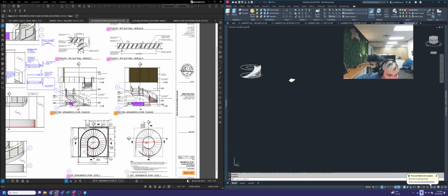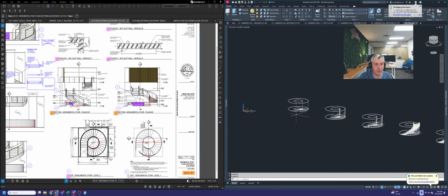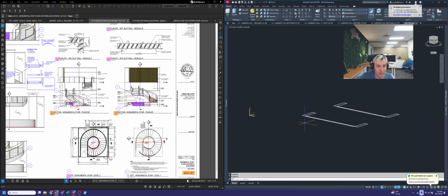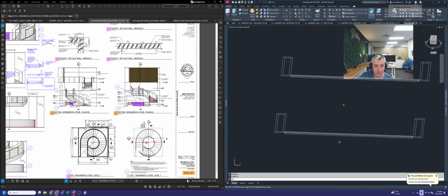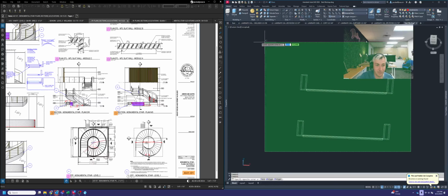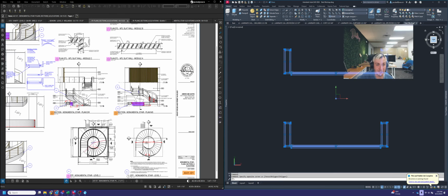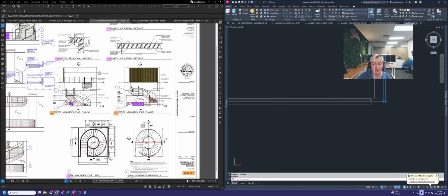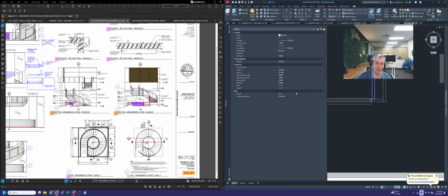One thing you can see is that what you really want to start with is your section view first. Anytime you sweep a model, it's pretty much the same deal. You want a model that has a bunch of closed polylines. Each piece of geometry needs to be closed. If I click on that and go into properties, you can see that they are. If you're dealing with something that's not closed, it's not going to sweep it as a solid.